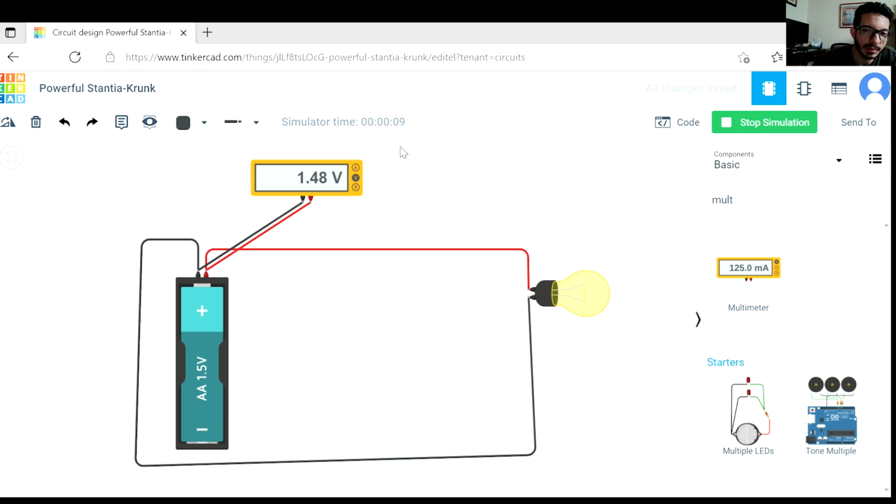As I said, the software Tinkercad is designed by the engineers to show some loss by running the circuit, because the load will turn some energy to heat and have some inefficiencies. But very likely when you get an actual multimeter, you can pretty much measure 1.5 volts, or sometimes much less if you don't have good contacts. The point is that if you want to measure the voltage, you simply put your probes right there.